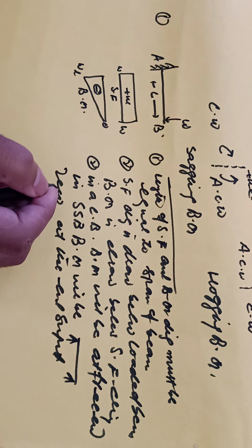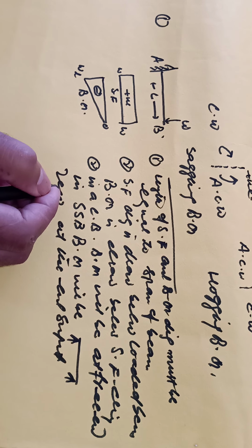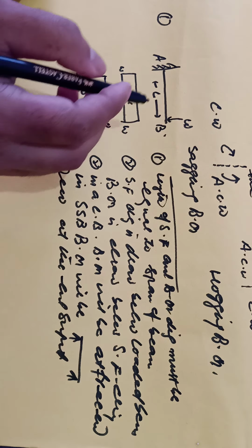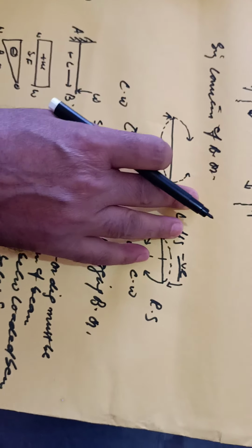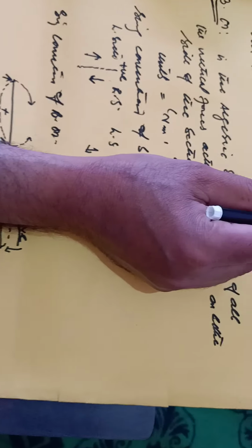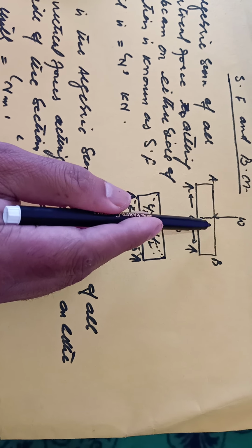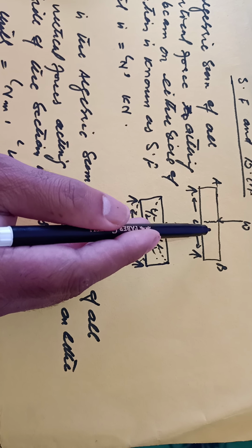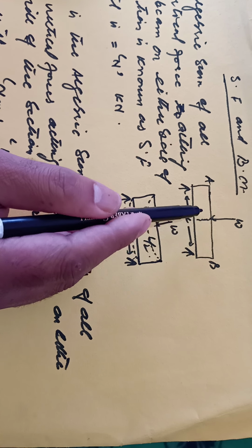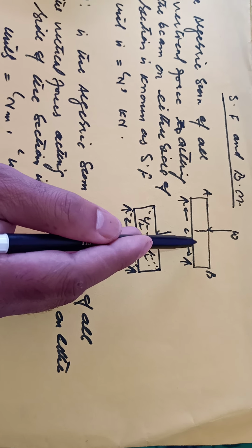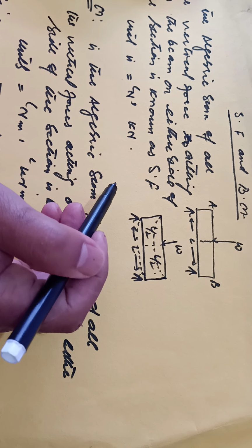Another point is, calculate. Here I have put only one vertical load. There may be so many vertical loads. Calculate shear force and bending moment at all critical points.